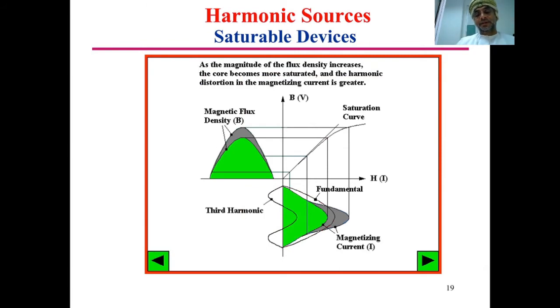But now, if we look at the current that will be taken by the transformer, it takes a current that will be provided to the load through the secondary, but it also has to create its magnetization. So it will take what we call a magnetization current, and that current will depend on the applied voltage, right?